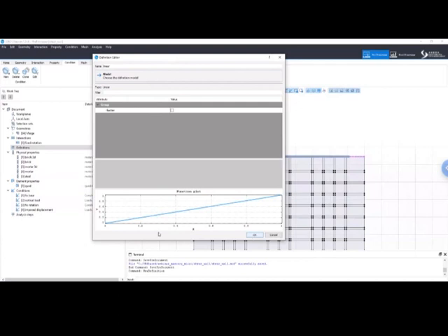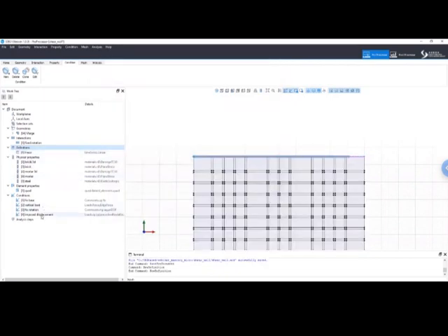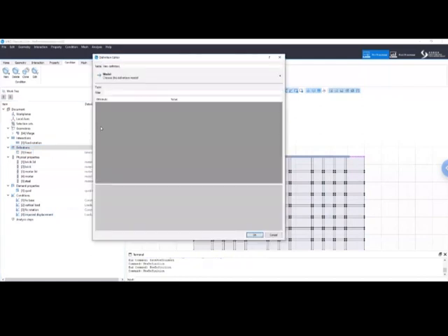And press OK. This is fine that we put this one from 0 to 1, because the reference value of the vertical load is the actual reference value. So the time series should go from 0 to 1. Now, on the other hand, the imposed displacement has a reference value of 1. So we will apply the total displacement in the path time series. Why? Because we have the values from the reference. Okay, let's call it cyclic.